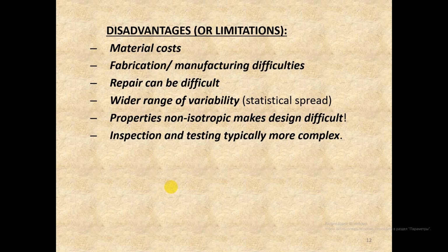Therefore, it's necessary to very carefully prepare the concrete surface to ensure reliable bonding, and this is routine work that must be carried out before strengthening. Also, issues of reliability of this alternative method for strengthening building structures by fiber reinforced polymer materials have yet to be properly defined.